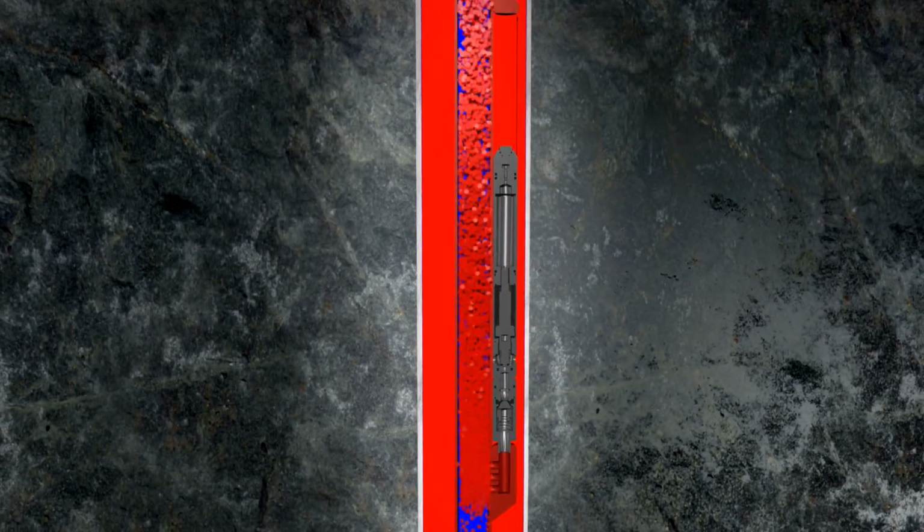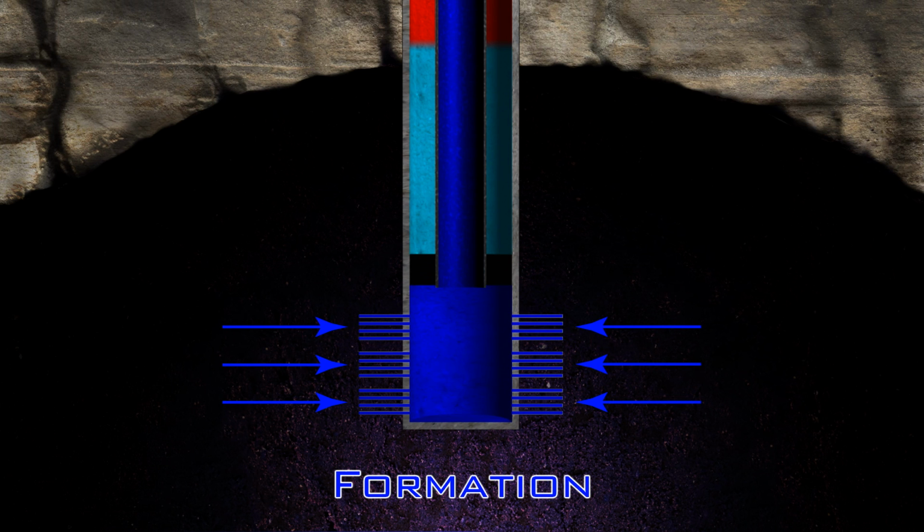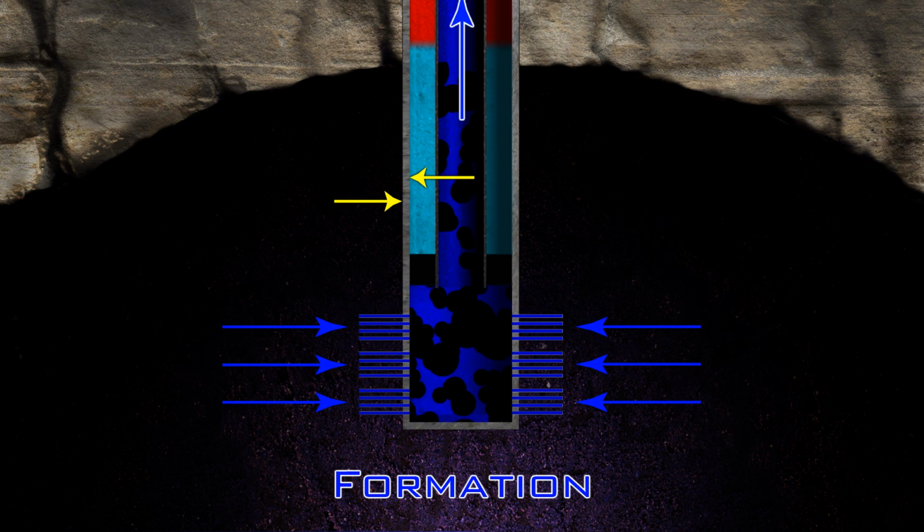As the gas enters the tubing string through the valve, it creates aeration, or a bubbling effect, in the liquid column. The gas bubbles expand as they rise to the surface, displacing the liquid around them and reducing the density and weight of the fluid. This decreases the flowing tubing pressure, creating a differential pressure between the reservoir and the wellbore, and allowing the well to produce at its optimum rate.